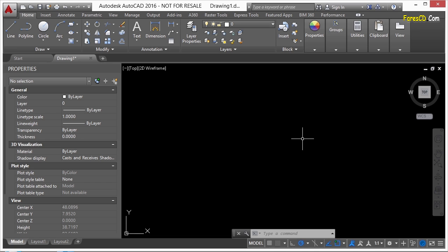But I want to talk about these lines. The commands are called construction lines and rays. Now, they both work almost exactly the same way. Essentially, AutoCAD is drawing a line with a length that's equal to infinity. That means it extends forever, essentially. Construction lines extend in both directions to infinity. A ray has a starting point and extends to infinity from there. Both are found in the Home tab.